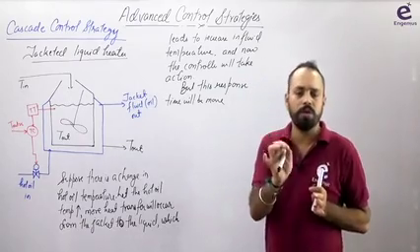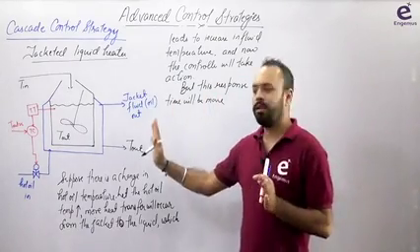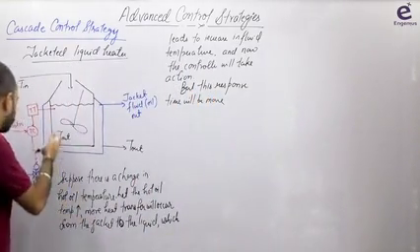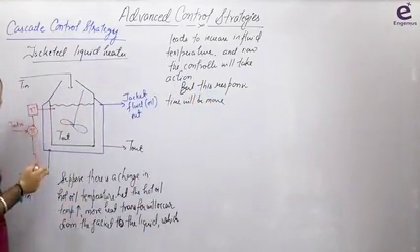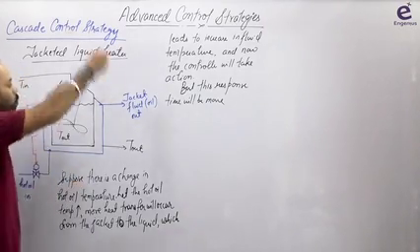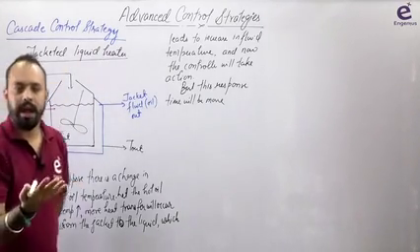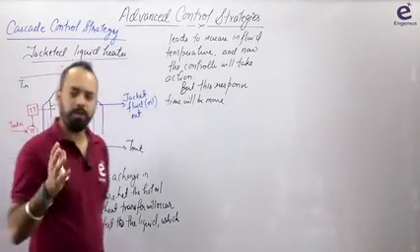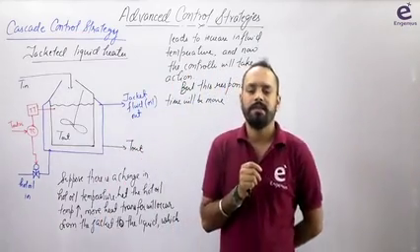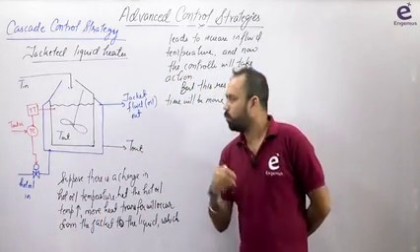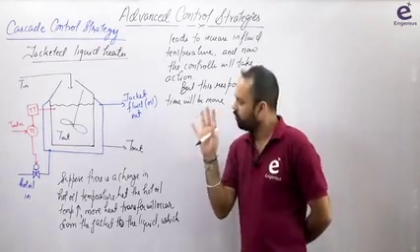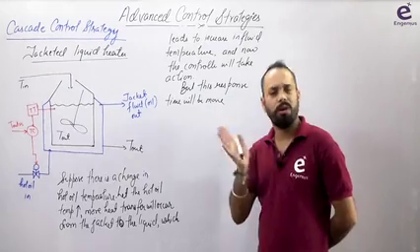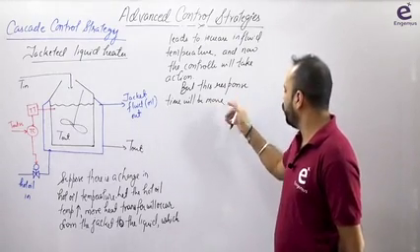So that is why I wanted you to know that even in this case you can be happy with the feedback control action. Now it totally depends on the time of all these individual elements. Somewhere, if there is more lag, that lag will add to the lag of the whole process, obviously, and then your control variable will be deviated from the set point for a longer period. My point is, it is not that without cascade control the reactor will burst, nothing like that is going to happen. It will work fine, but it will be away from the desired value of the set point for a longer period. But this response time will be more.